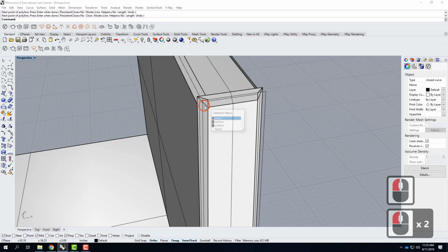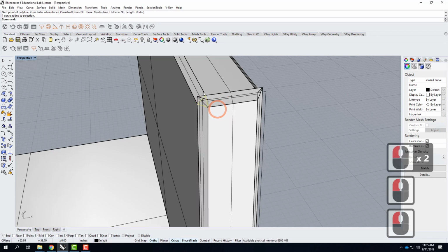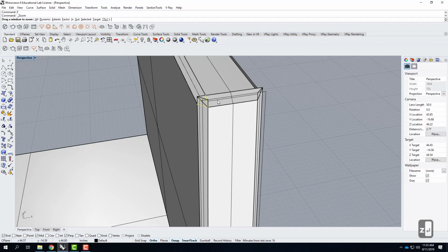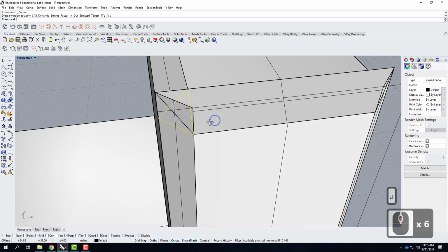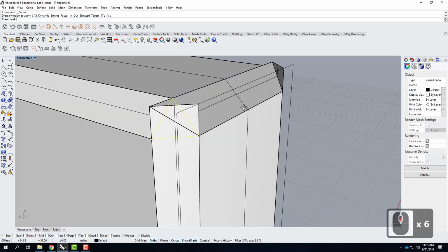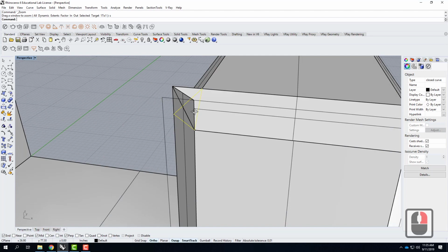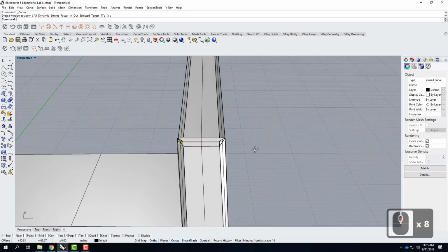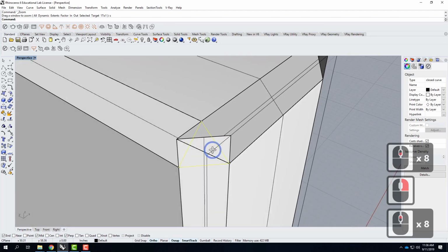After you have the triangle, we're going to select it, and then we're going to recenter our view to that object. So I'm going to type Z for zoom, followed by S for selected. It's right there, selected, and then enter. And now our view is centered around that triangular object that I just drew. So we're no longer trying to zoom somewhere else. We're not trying to orbit around some other place. It makes it really easy to work with.